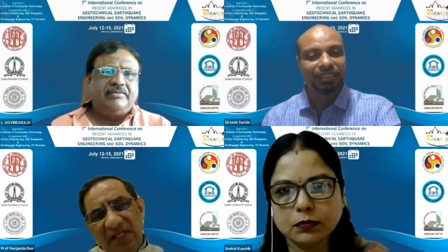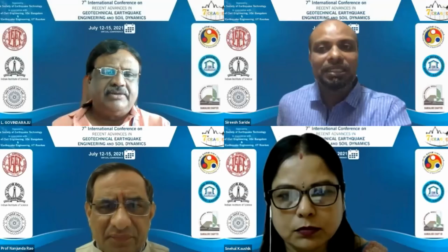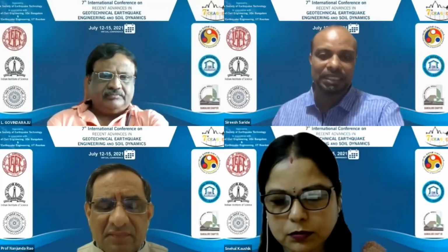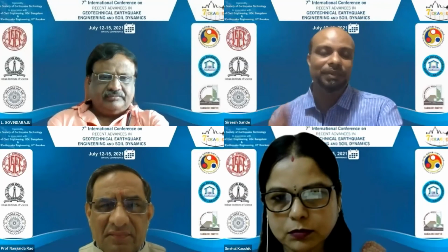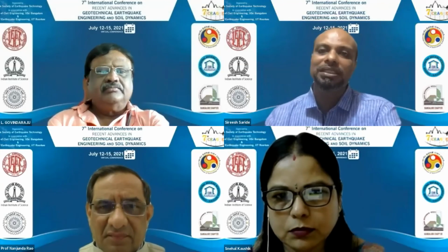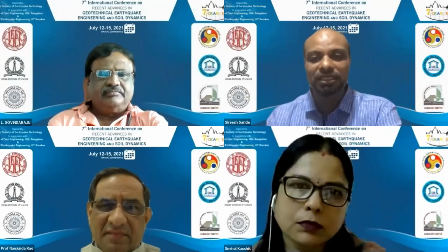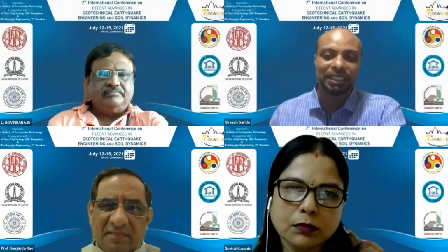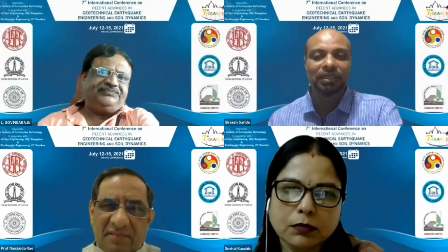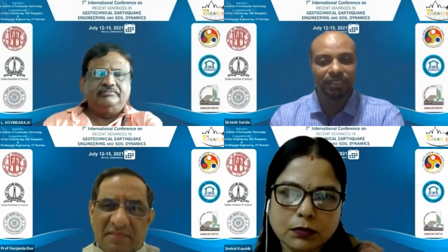But is the sodium silicate necessary here, if the fly ash is quite good? Except Neyveli, in India, most of the fly ashes are class F fly ash, which has very low calcium oxide content, about 1 to 2%. So they cannot directly participate in CSH or CAH gels. So what we have looked at is NASH gels, like sodium calcium aluminate silicates. Because these are low calcium fly ashes, we have to rely on that geopolymer combination.